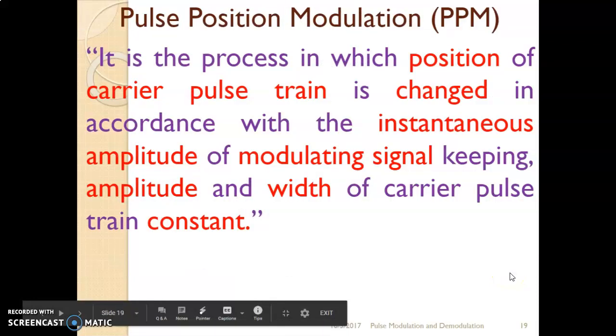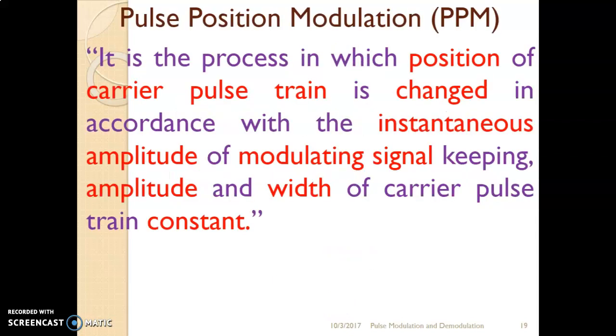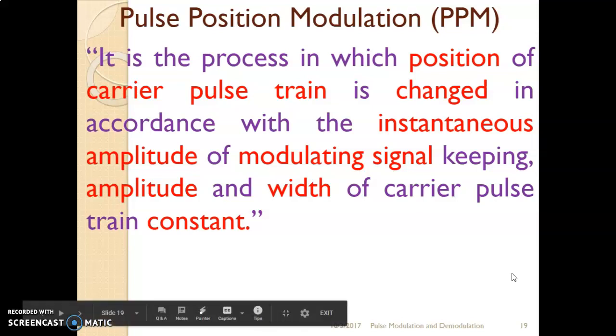So in the previous lecture, we studied pulse width modulation, and we saw that an important application of pulse width modulation in industry is power transfer, to deliver power to the load. The PWM signal consists of variable duty cycle pulses, and because of that the amount of power transferred to the load can be controlled, and it is used in the industry.